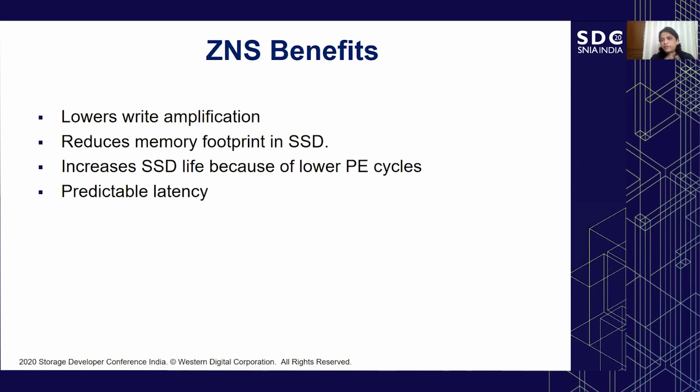But with ZNS, we have eliminated the device level garbage collection, and hence these activities are not happening on the drive, and the latency is predictable using ZNS.